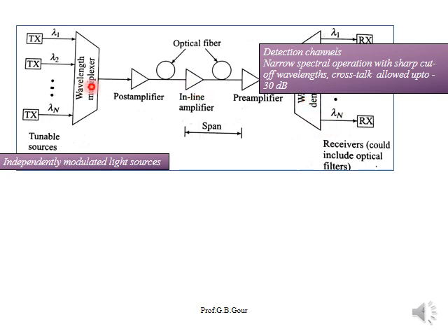So these are the first two parts you need to explain, and then remaining between, you can see pre and post amplifiers are there. Let us see how to explain them. Here you can see the post amplifier. Post means it is the first amplifier which receives the output of the multiplexed signal, the multiplexed wavelength signals, lambda 2, lambda n, whatever signals are combined. That signal is first received by this amplifier, which is located at the output of the wavelength division multiplexer.